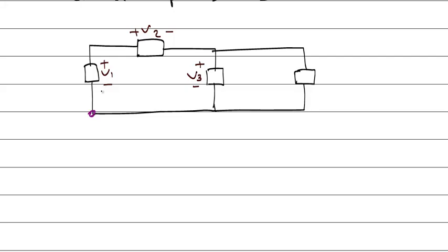It means while following the path, if you see first a minus sign, it means there is a voltage increase. If you switch from minus to plus, like that, minus to plus V1, it means there is a voltage increase. So you should write plus V1 and continue. You see a plus minus, it means there is a voltage drop. The right side is lower than the left side. So you have to write minus V2 and continue.